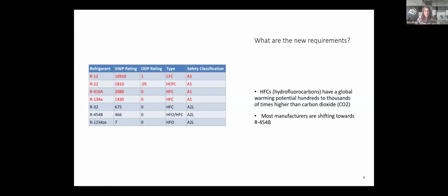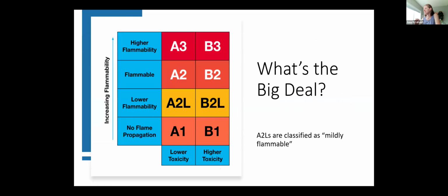Okay, next question. Any insights into the future of A3 refrigerants being allowed on monoblock type equipment setups? Yeah, that's a really good question, and it's one that I have as well. As you see here, the A3 refrigerants have a higher flammability rating. There's still that lower toxicity, they're the A classifications. And we do see a shift towards those, particularly within the monoblock equipment setups.